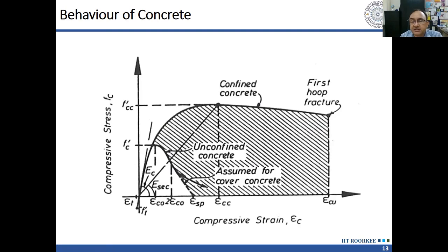In real structures, we cannot provide sleeves. We do not provide sleeves. But what we do, we provide stirrups. And those stirrups provide the confinement. And when the concrete is going to get crushed under earthquake or under any other loading in compression, the hoop will rupture, the hoop will fail. So we have to understand that this transverse reinforcement is the key to concrete ductility during earthquake, and its failure will govern the failure of concrete.